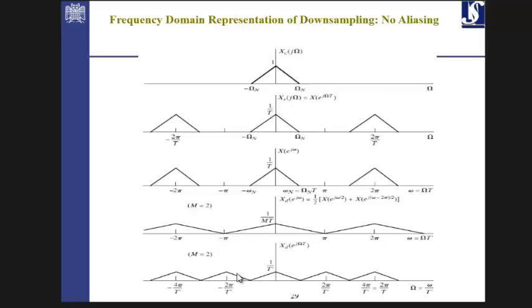But what else happens is that this bandwidth is actually extended 2 times, or M times, depending on the M rate of downsampling. So here you see that the frequency spectrum is actually getting wider. And it has the danger of overlapping with the consecutive patterns of the other periods. So in downsampling, if M is not chosen wisely, the result would be overlapping of the consecutive patterns and aliasing. So if we have such a thing, we need to know already that M should be sufficient.